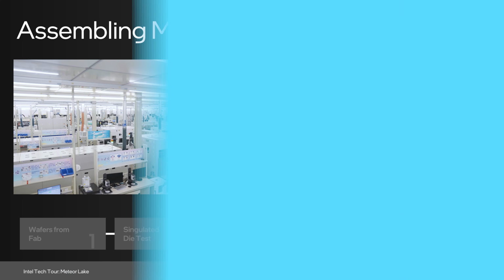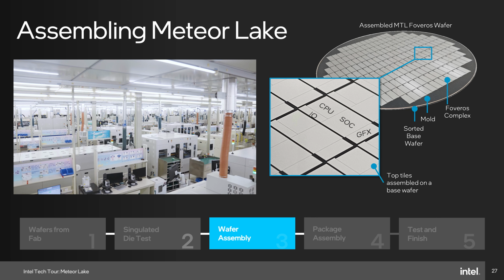I would say Intel is very, very good at singulating silicon and sorting it. We have an incredible sort platform. So all of the silicon that is considered a top die that goes on top of the interposer, it's all die prepped first, which is a very mature technology. And we can also sort it. So only known good die are placed onto the wafer as it goes through the wafer level line to finish its processing. And then after it's finished, we call it a stacked die. After the stacked die is singulated, you can sort it again. And then you can make sure that only good stacked die are going onto your package in assembly. And that can be extremely important.